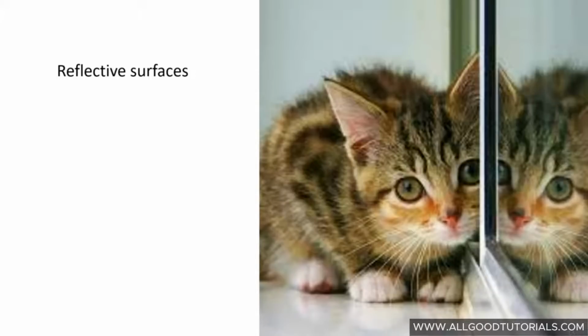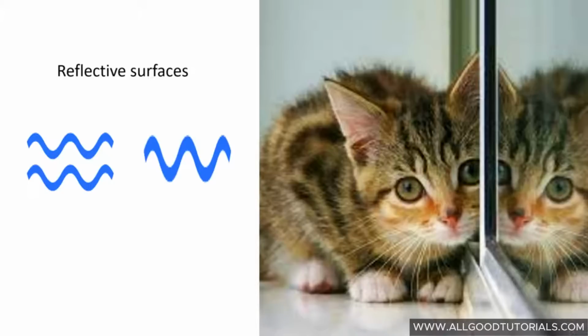Your radio signals are just like light, and they can also bounce off highly reflective surfaces such as your mirrors and any other metal objects in your home. You can think of your radio signals traveling in waveforms, just as light travels in waveforms. If that waveform reflects off a surface, then these waveforms can be combined. In this first illustration, the waveforms are actually reinforcing each other and strengthening the waveform. When that happens, you actually receive a stronger signal. But conversely, a reflective signal could be combined with other signals to actually cancel the signal out.